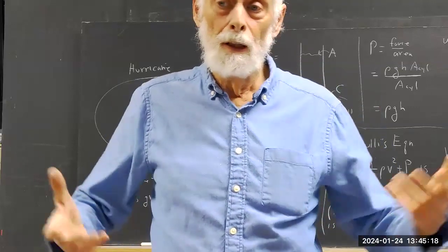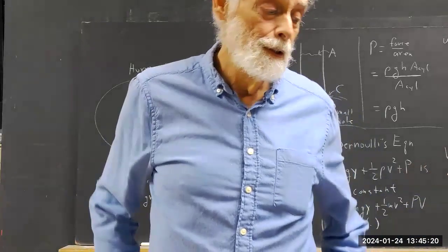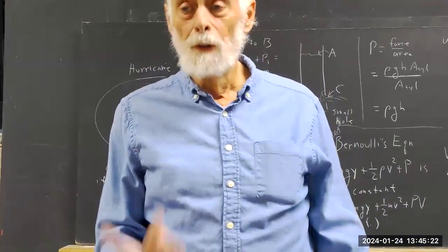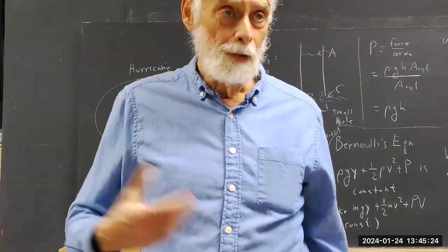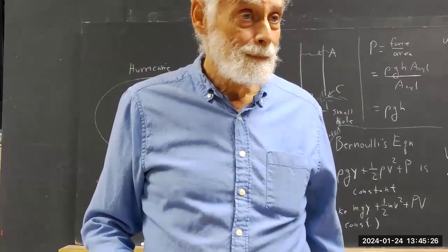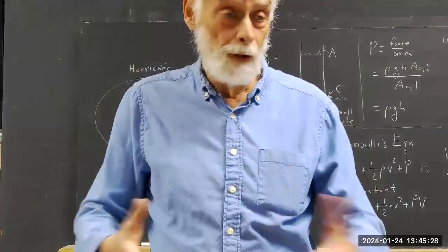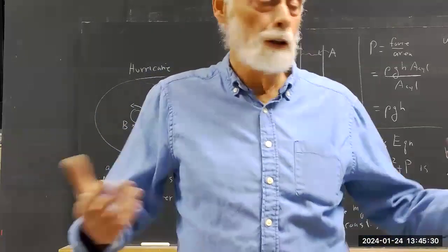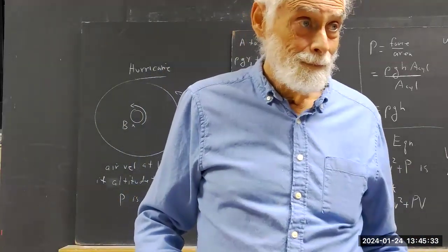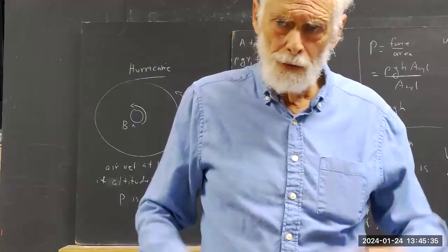So you write down the expressions for the pressure under and the pressure above, take the difference, and then calculate the volume of the thing multiplied by the density of water, and you're going to get the same thing. So for a rectangular solid, it's easy.